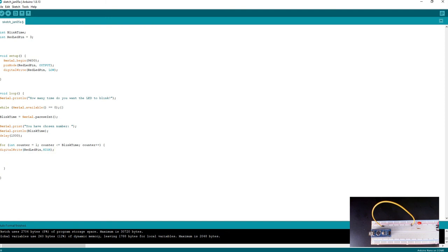If you want to do a blinking pattern, well, the logic would be once high, you want it to go low. But you don't want to go super fast, so you're going to put in a function, and we'll say, let's wait a second. And then once the second passes, you still go and ask the computer to write to the red LED pin, but this time you want it low.